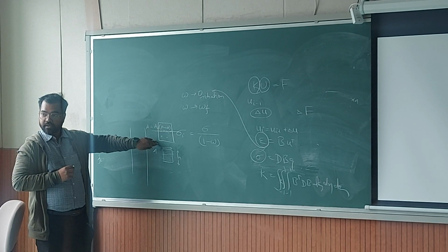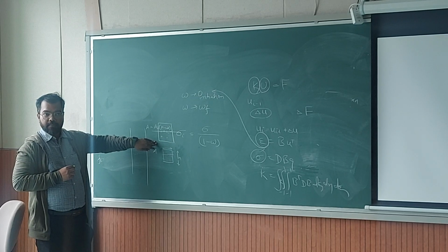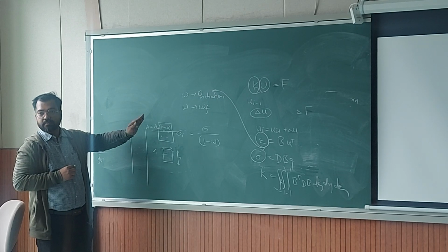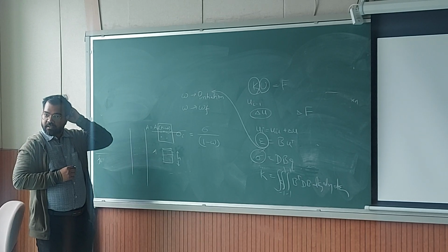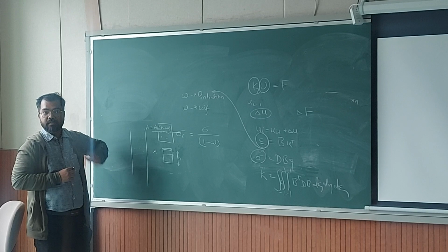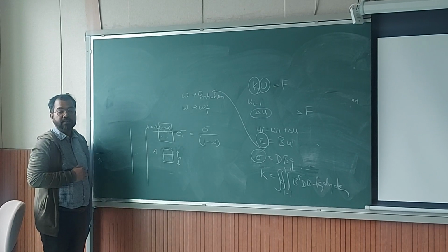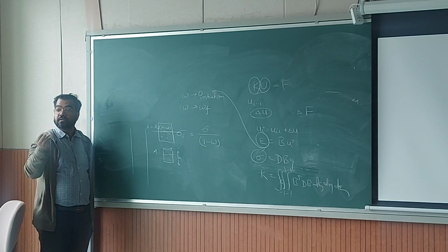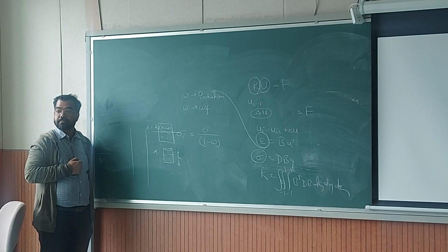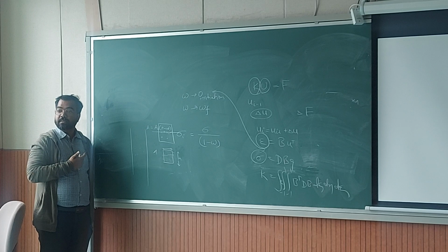So this is what I am doing, right? I am correcting the area by the amount of damage parameter, and I am really not simulating any void in the finite element analysis. There is no information of location, there is no interface of void with the element. No new elements are being generated.